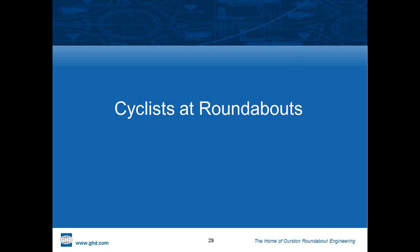Cyclist and bicycle accommodation in roundabouts. Maybe just a point about cycling safety. At least European studies, there's not much yet in the U.S. or Canada. The European studies show that cyclists have an increased incidence of involvement with motor vehicles in roundabouts as compared to traffic signals. So when we talk about all the benefits of roundabouts compared to signals, the capacity improvement, the safety benefits, and air quality and so on, the one that we struggle with is the cyclist at roundabouts.